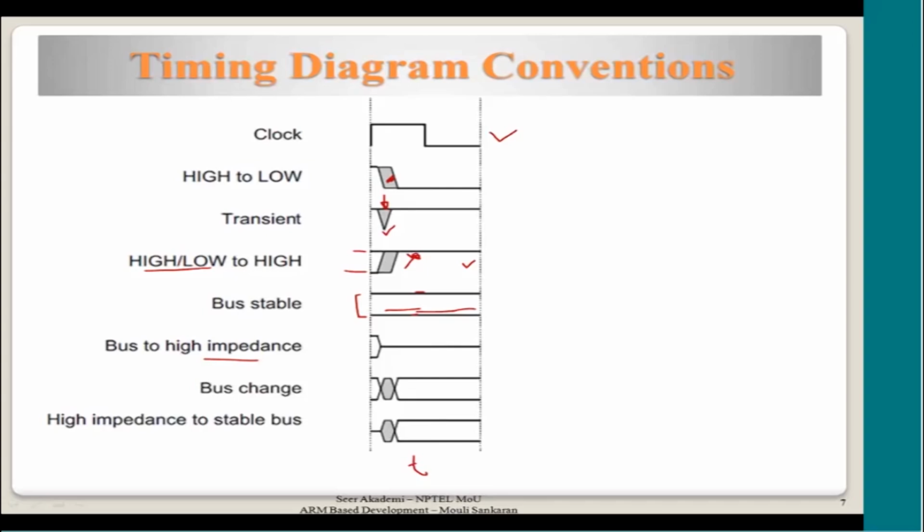And the high impedance state is a very important property for supporting a low power design, because once the bus is in high impedance, nobody is driving the bus, so it is not drawing current, and its capacitive effect on the circuitry of the system is also less.